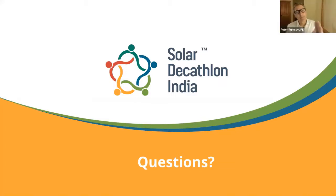Yeah, so the peak solar radiation might be at 12 noon, on, I don't know, sometime in June, July or something like that. That might be in the weather data, the peak, but the building peak might not be that same day or that 12 noon. It might be 3 p.m.